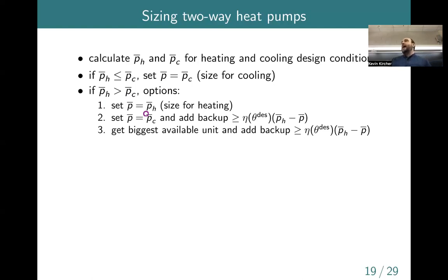Why that matters is a little bit subtle, but let me see if I can briefly explain it. If you have a huge air conditioner serving a small thermal load, it will turn on when it gets hot inside the house. We talked about thermostatic control last week, right? When the temperature rises above some limit, it turns on, and then it'll really quickly cool the house down. So within a matter of minutes, boom, you've dropped from, say, 80 down to 76, and then it turns off. So it's doing this turn on, turn off thing very frequently.